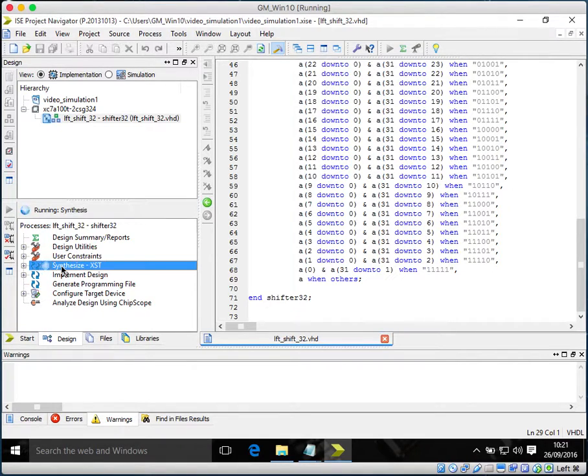So what my code basically does is that it takes in a 32-bit input and gives out a 32-bit output, and the 32-bit output can be shifted from 0 to 31 times, and this is chosen by a user-interpreted 8-bit bus, which can be a universal bus in the system. And since I need only 5 bits to perform the actual shift,